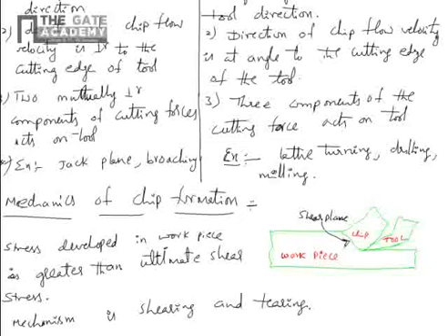Whereas during machining of hard and brittle materials, discontinuous chips are produced because they have lower toughness, allowing the crack wave to propagate easily to the surface, producing small chips or breaking the continuity of the chip. During machining of soft workpieces, the magnitude of the energy wave is lower due to lower strength of the material, and it can't propagate to the surface, whereas in brittle materials the energy wave is larger because of higher strength of the material and can propagate up to the surface easily.